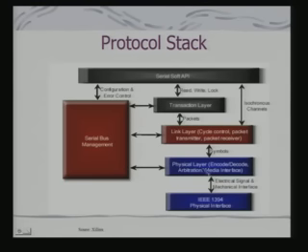Then you have the physical layer, which provides the encoding, decoding, arbitration and media interface, because the data, when it has to flow in and out, has to be encoded and decoded appropriately. Then you have a link layer, which controls the packet transmission and packet reception. This is a transaction layer, which actually carries out the read write transactions over the bus.